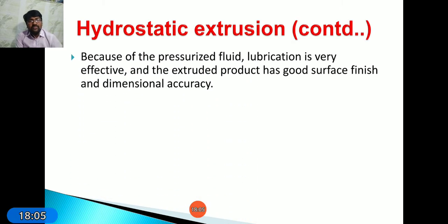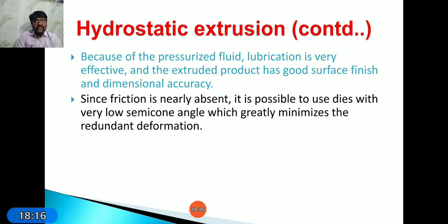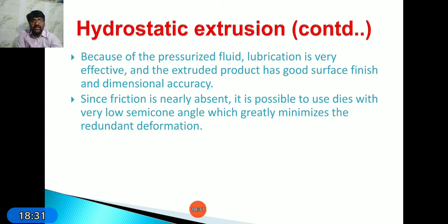Next, because of the pressurized fluid, lubrication is very effective and the extruded products have good surface finish and dimensional accuracy. Since friction is nearly absent, it is possible to use dies with very low semi-cone angle. Okay, like that we can greatly minimize the redundant deformation.